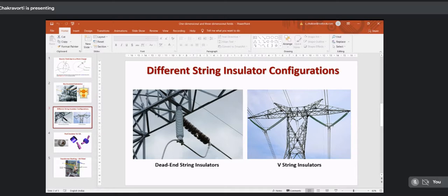Therefore, this is also a two dielectric arrangement. So you can see that in our life, it is very difficult to get a single dielectric arrangement. Where can we say single dielectric? On the right side, if you just move away from the tower, then these conductors are running, and this conductor is surrounded by only air. So if you compute the field somewhere away from the tower, then it is a single dielectric arrangement, because only one dielectric is present, that is air.